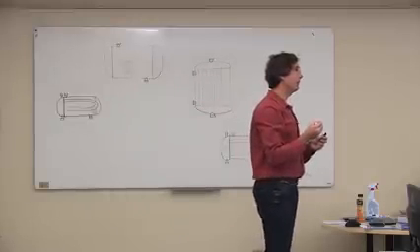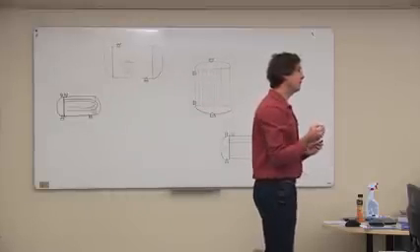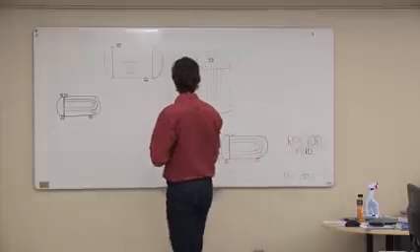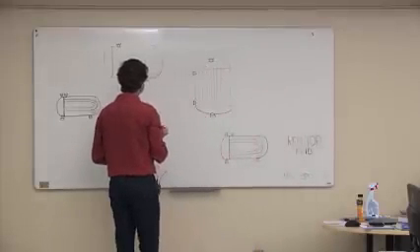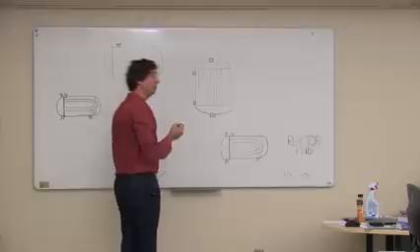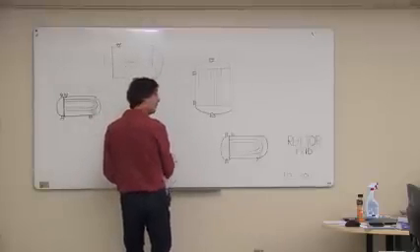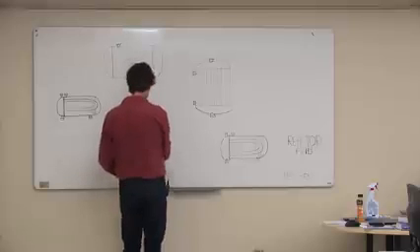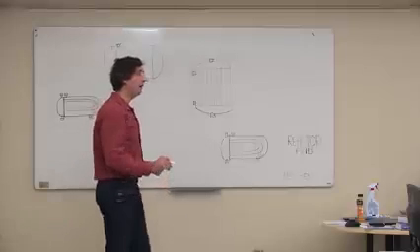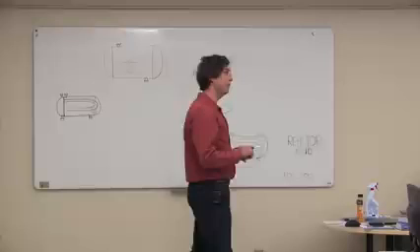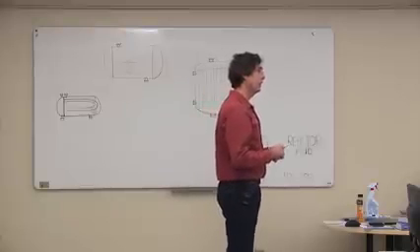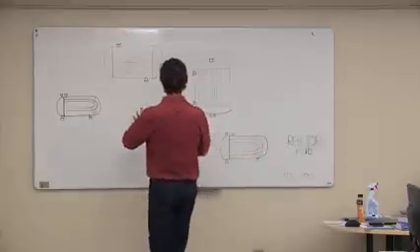What do we need a pump for? Pump water through the jacket? Okay. We might. So if we need to do that, we're going to need to put the pumps probably at ground level. We're going to need to put them in here. I think we can run the jacket with a thermosiphon. It might be debatable. But I think we can run it without actually having a pump.